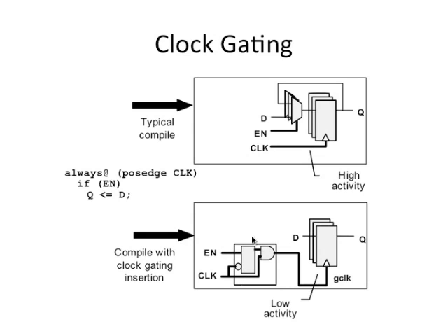Now, an important thing whenever you muck around with the clock is that you want to ensure that you don't create glitches in the clock network. If you modify the clock network, you should not create glitches, because every edge in the clock input is very important. The system reacts to an edge because an edge is such an important thing. So you should not create spurious edges through glitches. Right? Then your whole machine will basically go for a toss.